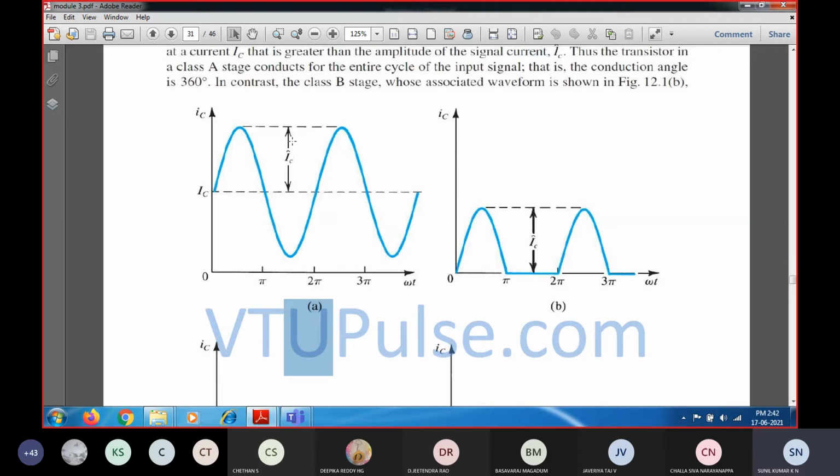For that, if you plot a DC load line, we have the output characteristics, a family of curves of collector current for different VCE. Upon suitably selecting the Q point exactly at the center, for a given input signal you will get full length amplification without any distortion.